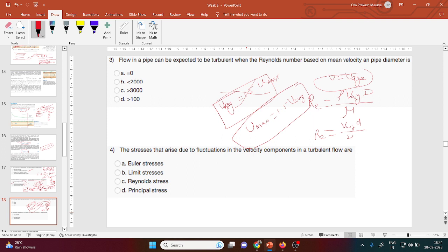Which one is correct? If the question gives 5 meters per second at the end region, do we need to convert it into V average using this 1.5 for calculating the Reynolds number, or can we directly take that as V max?